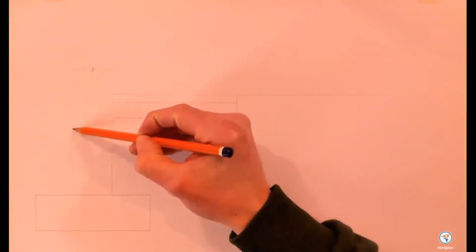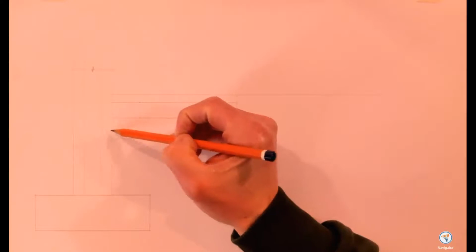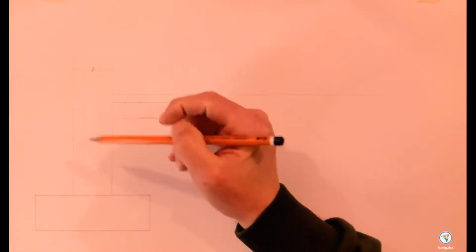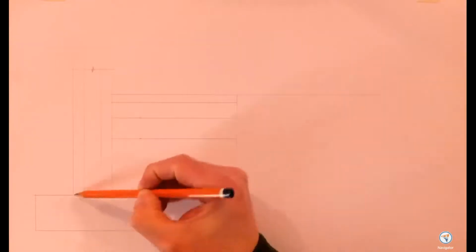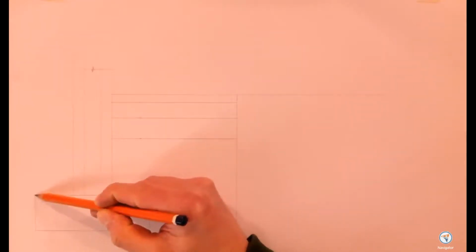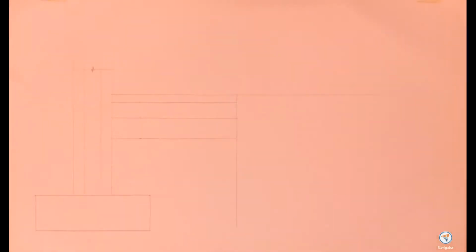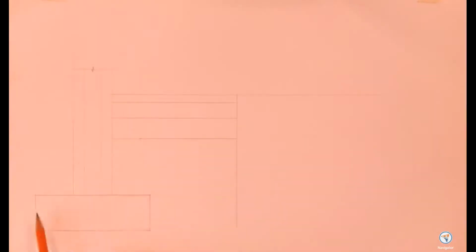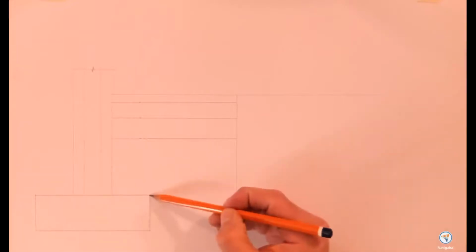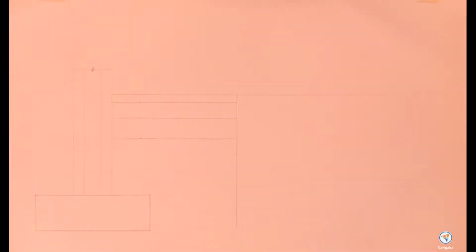So, starting off the drawing, I've put in the external wall, just 10mm, 15 and 10 for our external wall. Our foundation then, I've stepped out 35mm each side of the external wall, and the foundation will be 35mm thick. What I'm drawing is a 350mm external wall, and that makes the real life version of the foundation 1050mm by 350mm thick.